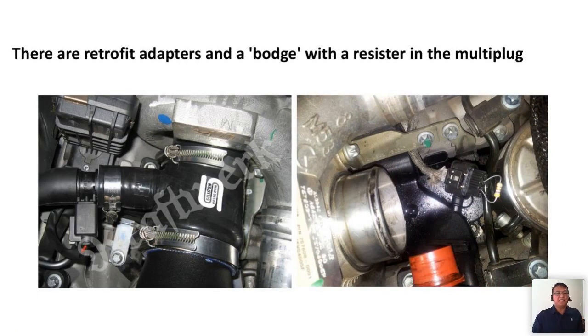And this is a modified adapter, or what you call it, a seal for that intake for the turbo. And if you can see there, they put a resistor just to check that the fuse will not blow again. In some cases, some customers, because I know this is not a very easy job, just leave the resistor there and leave the car running with the engine light on.